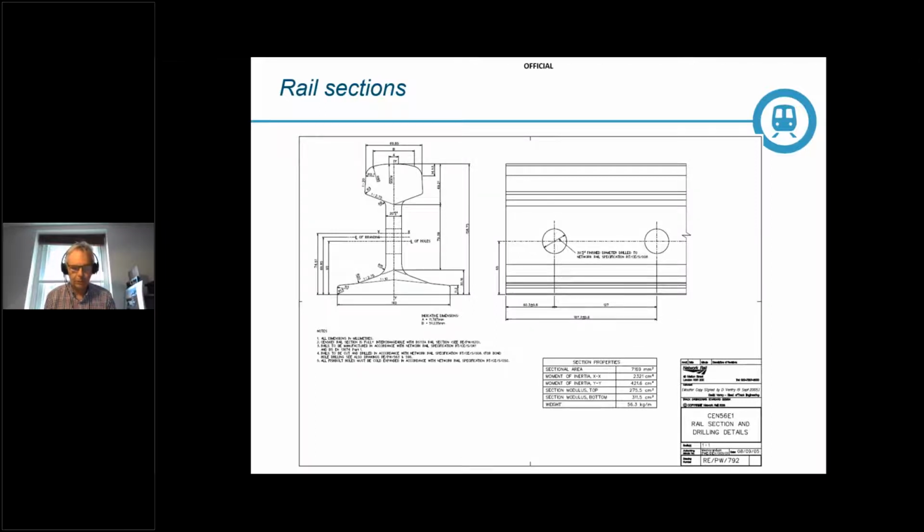And this involves a compromise, and we've seen that as carbon content is increased, we get stronger, more wear and crack resistant rail, but at the expense of losing fracture toughness. So let's consider the effects of section on strength.